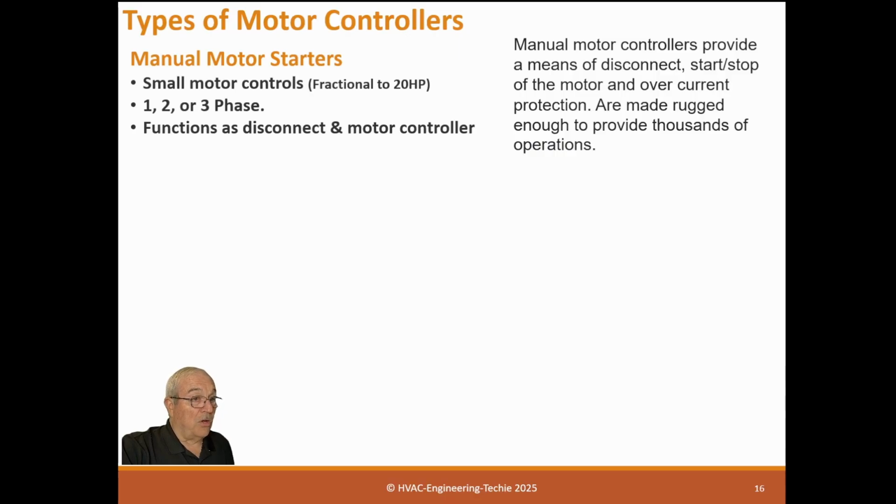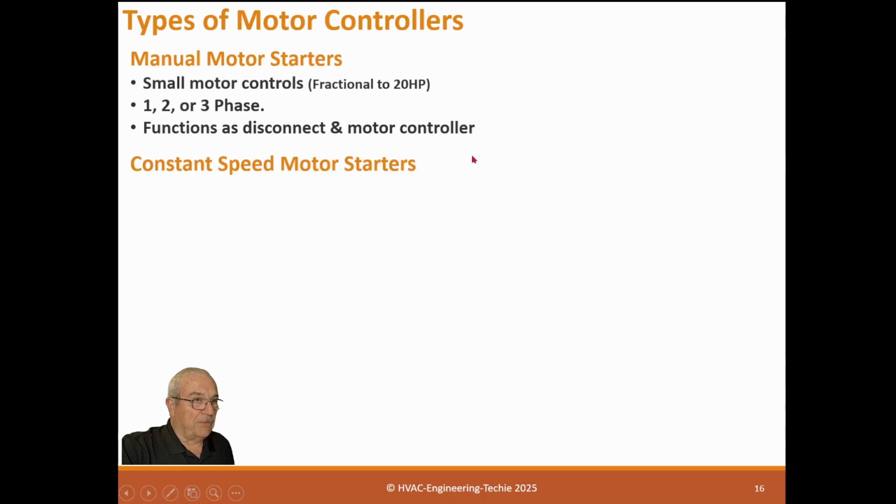They may look like a light switch, but I guarantee you they're not a light switch, because a light switch will arc. Well, when you turn on a motor load, it will arc. So basically we use these motor controllers instead because they're safe. They're guaranteed not to arc for the horsepower rating, and they're designed to take thousands and thousands of operations.